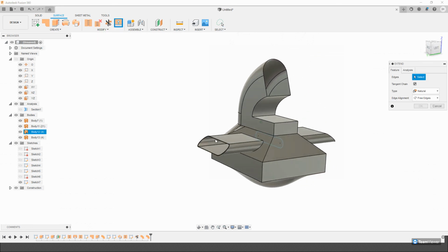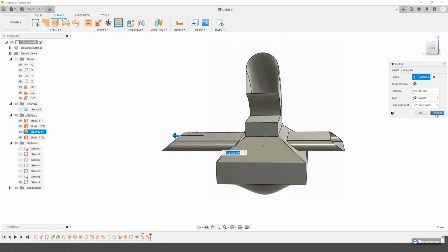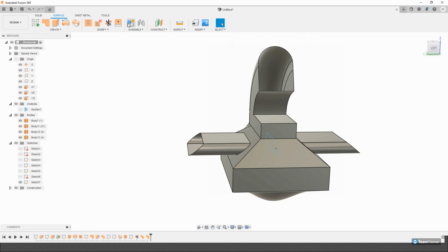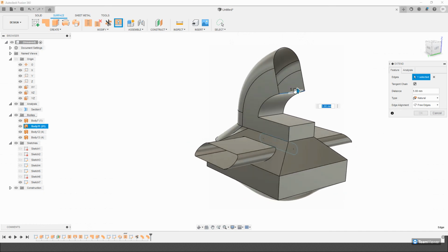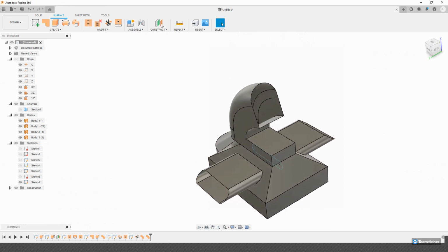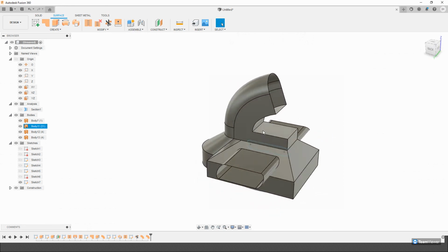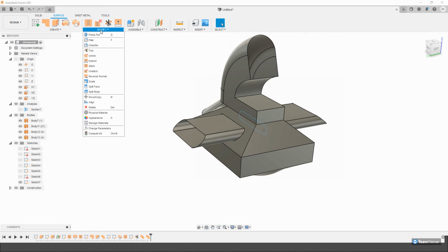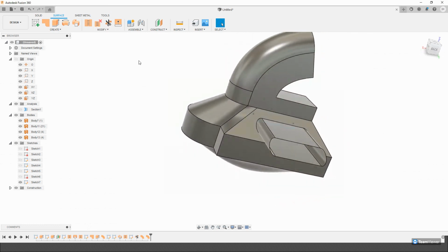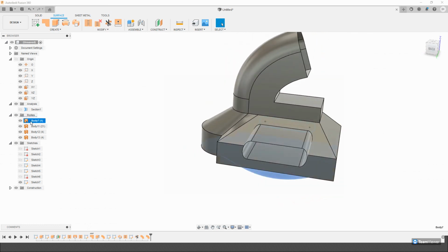The extend tool is something similar, but remember, it's just going to extend in the same direction that it was going anyway. So for example, if I had that, or if I have maybe there, just put that particular line, I can, oh, well, that doesn't work, but oh, that's part of a sweep. But any extruded surface can be extended besides your sweep. And of course, we can create what we want from this. So between that one, that one, that one, and that one, I can say stitch all of these together, and it makes them into one body.